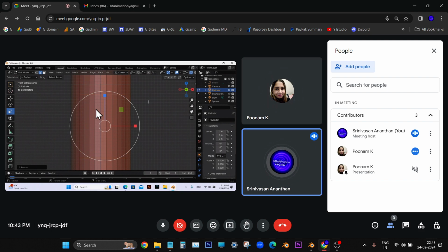Just now what you did is you clicked on one axis using the left mouse button, but you didn't leave the left mouse button. Without leaving it, you just typed 0 or 90, you can type 180. It will immediately change as per your requirement. So here we applied 0 and it became flat. We call this special manipulation. Now it has become flat.